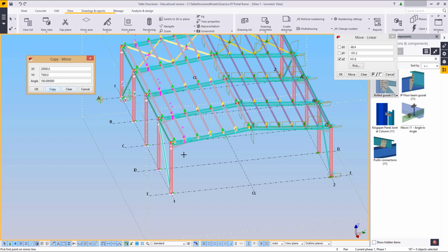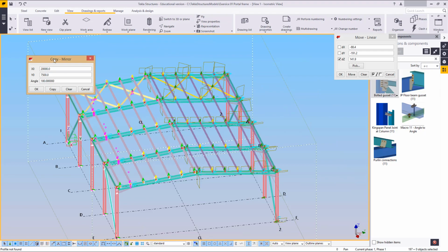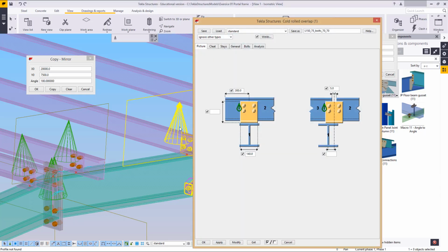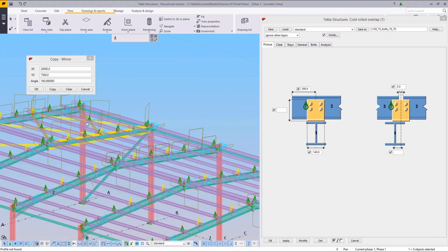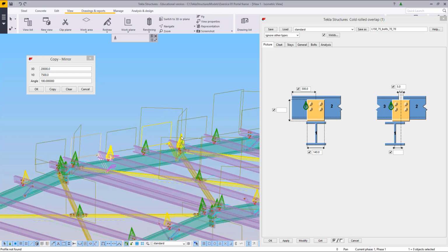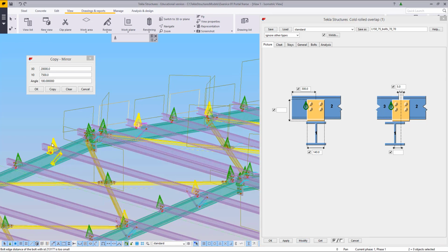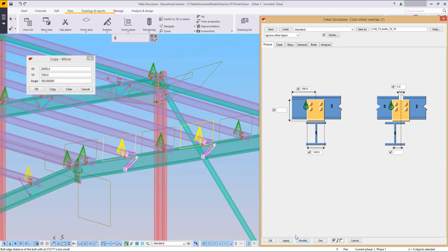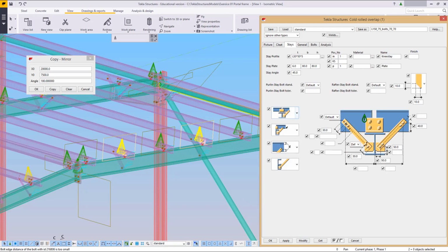Once this is done, we will need to fully inspect our new area to make sure that it mirrored over properly, as Tekla sometimes tends to cause small problems when it concerns components and mirroring. Let's quickly have a look here. Stuff like these two will need to go on that setting, and this setting will be over here, or simply open them up and swap this one around.